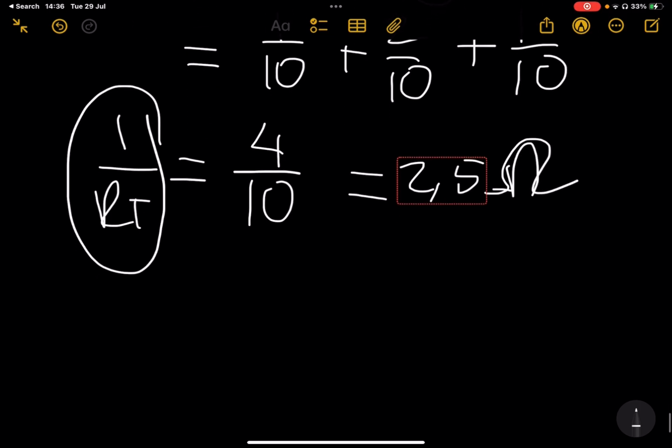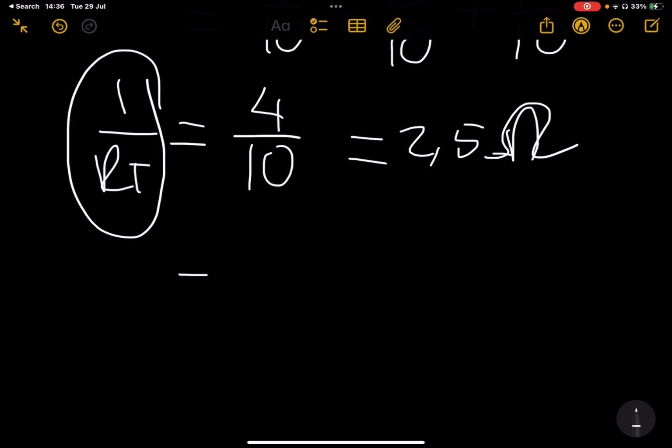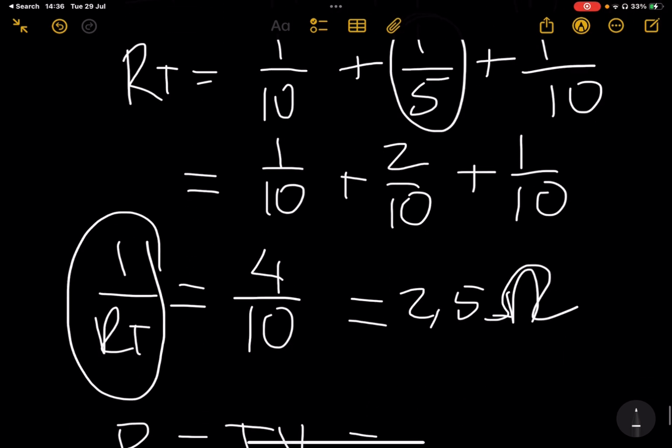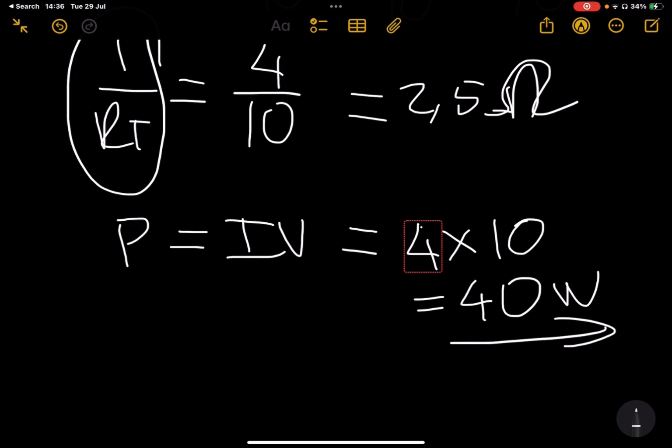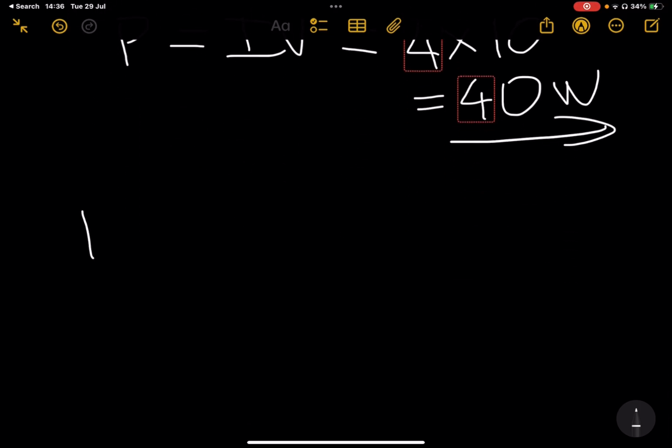All right, so let's go look at the power formula quickly. So P is equal to IV, right? This is the simplest one that I taught you guys, which is essentially, let's look at the total current flow, 4, times the voltage, 10, which is equal to 40 watts, right? Okay, cool. Now we've used P equals IV, but if we look at the wheel, we can write P as a few things. Let's express it not in terms of current, but in terms of voltage and resistance. And let's see if it proves to be true.